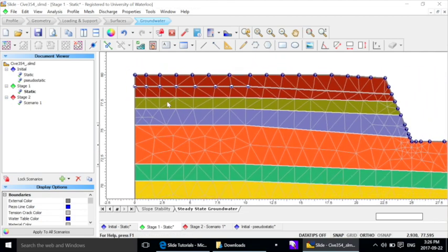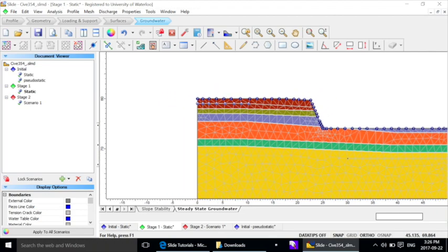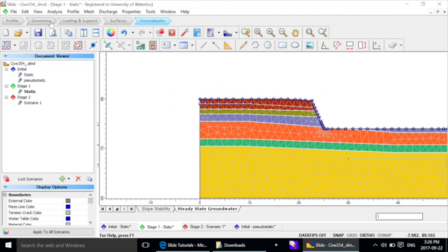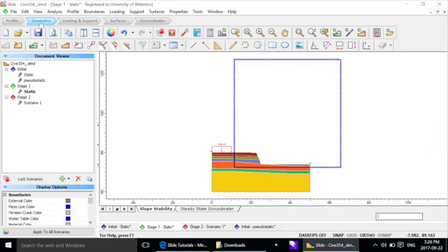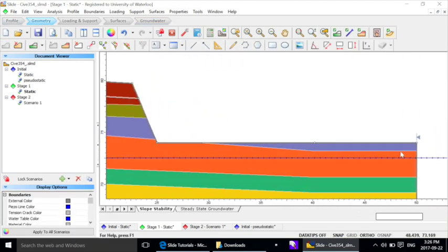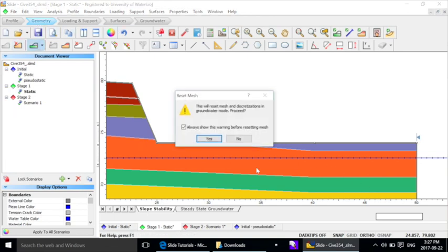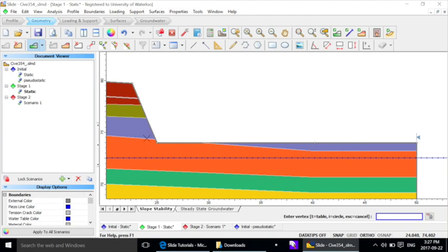And then there is one, oh, we have to go back because I forgot something important. In the document, there is one part where it is explained that for safety reasons, the water table should always be at least 1 meter below the bottom of the excavation. So we need to define another boundary in order to consider that option. Yes, so if this is 2574, let's say 2573. So that is 1 meter below.